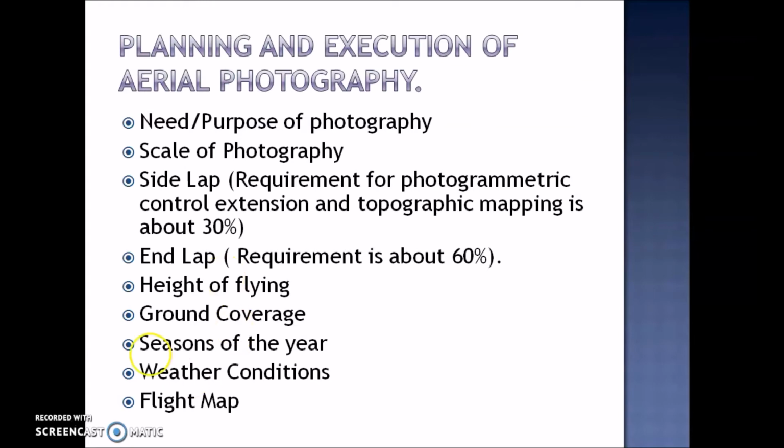Then the ground coverage has to be taken into consideration. Whatever the amount of area we are surveying, all the ground coverage has to be taken into consideration. And seasons are also very important. The altitude of the sun, fallen leaves from the trees, all these parameters are taken into account. If it is summer season, the altitude of the sun is a bit different and the sunlight will be different, so the photographic images and pixels and everything will be different.